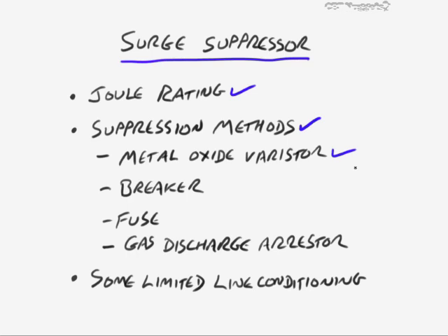But generally, they're designed to accept voltages up to about 6,000 volts, and they were supposed to divert anything above 200 volts to ground. The thing with these is, over time, and if there's been pretty kind of dirty power that goes on, where I know that sounds like, you know, a dirty politician or something, but if it's the kind of power that you're in a location where you get a lot of surges, it can eventually start to wear on these, and they don't have the same lifetime or reliability that they had when these devices were brand new. So they have some varying degrees of quality over the passage of time.